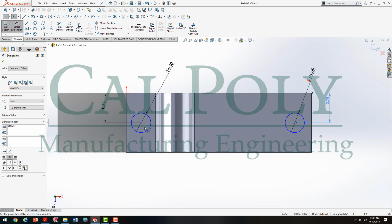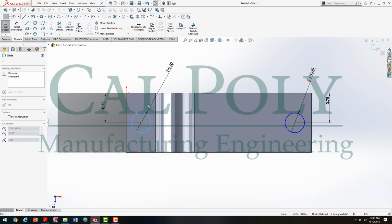So now, notice the circles aren't fully defined yet. They can't move up and down in respect to the y-axis, but they can move technically back and forth in the x-axis right there because nothing defines or places them there. So we need to do that with a smart dimension or a relationship technically. We don't have any features to relate the center of the circle to at the moment. So we're going to have to use smart dimension.